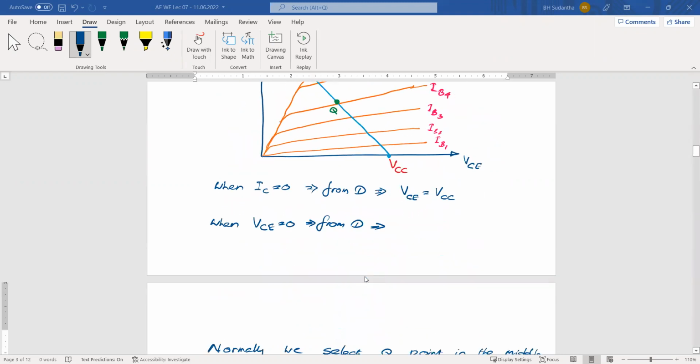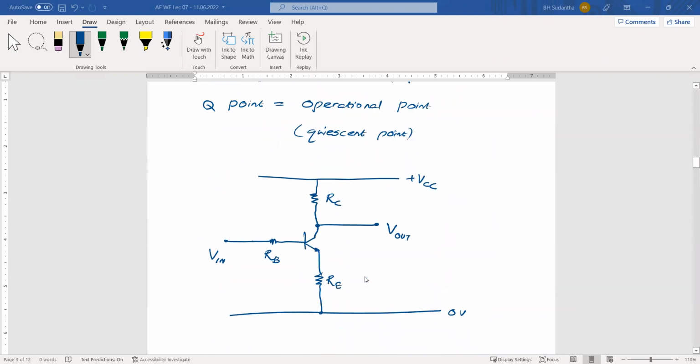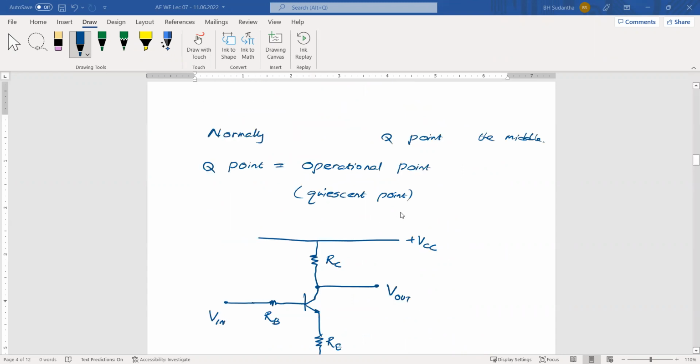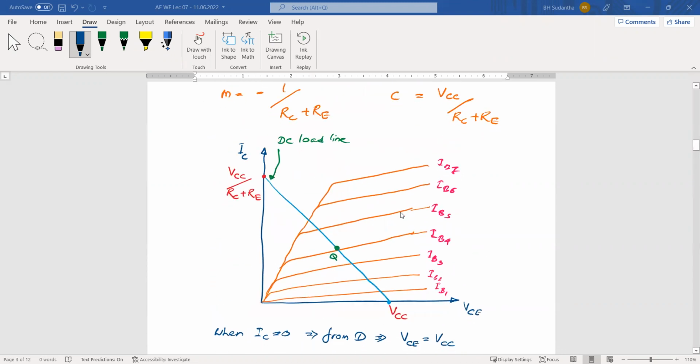If you don't have this base voltage here, the transistor cannot work there. Then the transistor will be moved to this side. This is cutoff mode. This is saturation mode, and this is the linear region. And when we want to use this transistor as an amplifier, we have to make sure that we are operating the transistor in this region, the linear region, the active region. Okay.